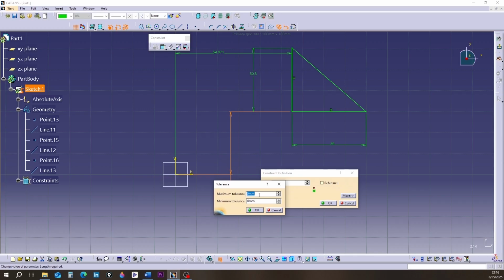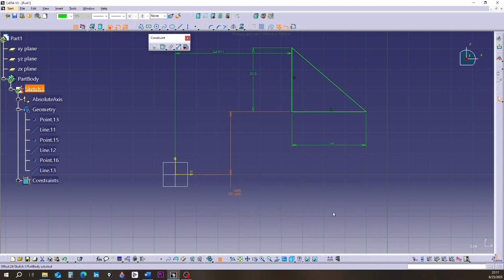Double-click on the upper box until it turns blue. Type the number 0.05 in it. Double-click in the lower box until it turns blue. Write the number 0.02 in it. Click on OK. Click in the main box. Click on the page and outside the dimension. It is observed that the number 30 was shown with 2 tolerances, plus 0.05 and plus 0.02.